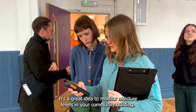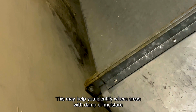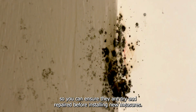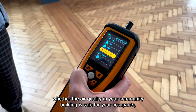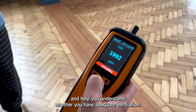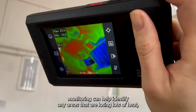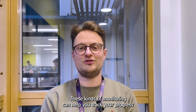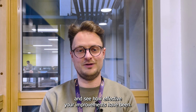It's a great idea to monitor moisture levels in your community building. This may help you identify where areas of damp or moisture buildup are occurring, so you can ensure they are dry and repaired before installing new measures. You can also monitor air quality. This can tell you whether the air quality in your community building is safe for your occupants and help you understand whether you have adequate ventilation. Simple temperature monitoring can help identify any areas that are losing lots of heat, therefore identifying priorities for repair or improvements. These kinds of monitoring can help you track your progress and see how effective your improvements have been.